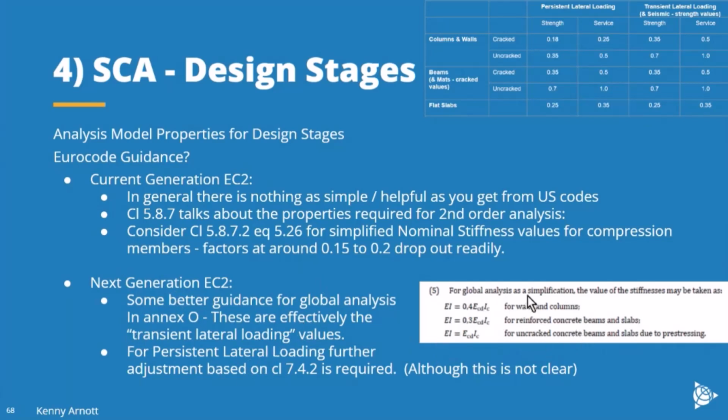What's not stated, or not clear from the draft, is that the guidance in the Annex is for the transient lateral condition. If you have a persistent lateral load condition, again, there's a further adjustment required, which comes from clause 7.4.2 in the new code.